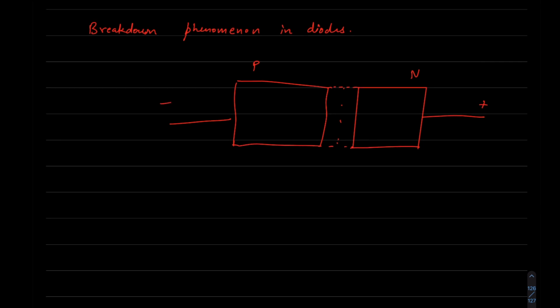So we know that the breakdown voltage is the largest reverse voltage that can be applied without causing an exponential increase in the current in the diode, right? Now, note that as long as the current is limited, exceeding the breakdown voltage of a diode will not destroy it. I talked about exceeding the breakdown voltage and an avalanche happening and our diode breaking down. That's not true.